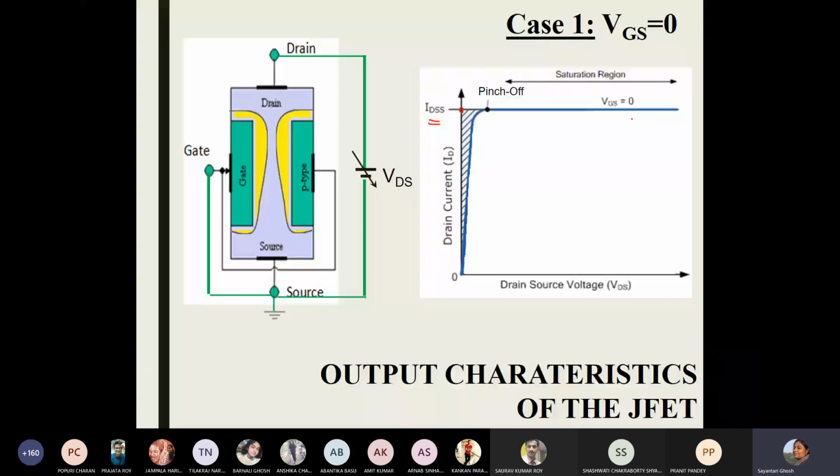So this is also a specific constant associated with a JFET. When you buy a JFET, these two values come specified. One is the maximum drain current, IDSS: I, drain to source, with the gate and source terminals short circuited, so the last S is for that. And the other is the pinch off voltage, VP. Okay, this is called pinch off.